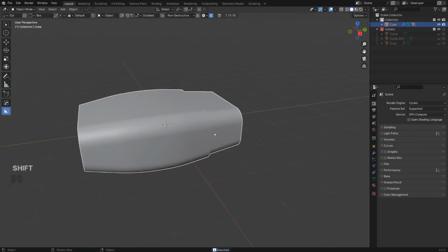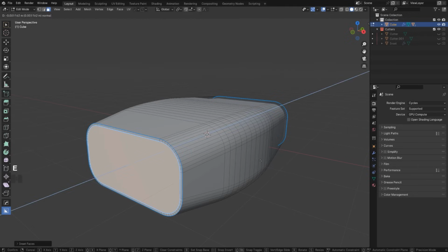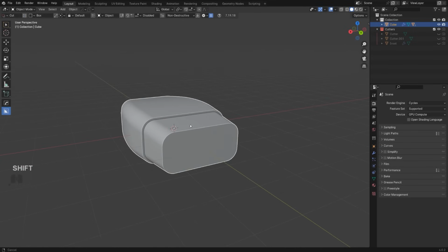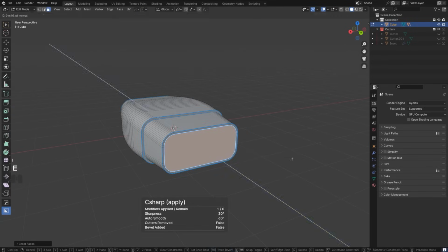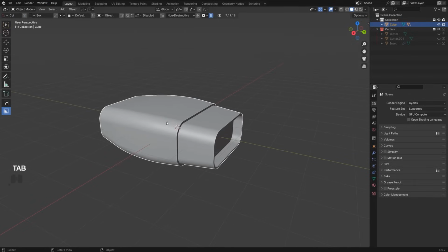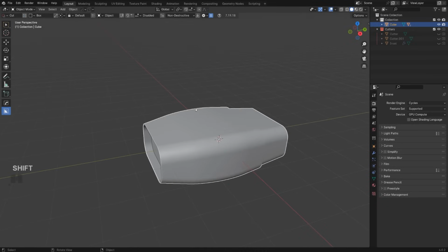Cool, that looks good. So here in the back, let's grab this face, I to inset, E to extrude it. You can go quite deeply, that's fine. And here too in the front, let's just apply this with Sharpen, grab this one, I to inset, and extrude it, okay? So we got something like this, which looks pretty cool, okay? So this is our starting piece.